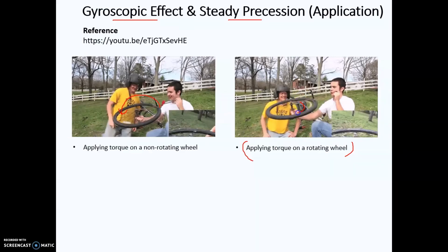First of all, the rotating wheel is rotated in this direction, therefore you should obtain the omega here. And this is where you have the H1, which is the angular momentum. When you apply the force upward, and this is the center, you can obtain the radius here. Radius crossed with the force gives you the torque. By using the right hand rule, you should obtain the torque acting forward in this direction.